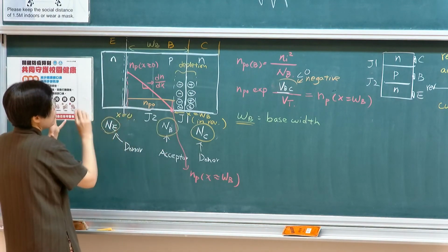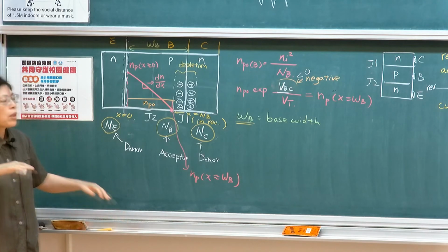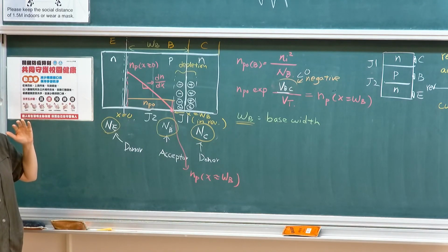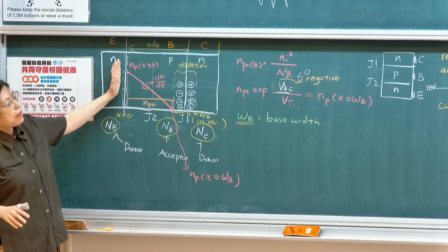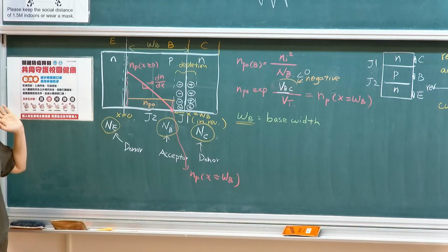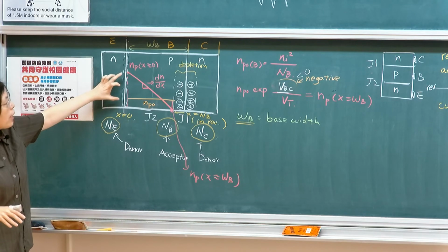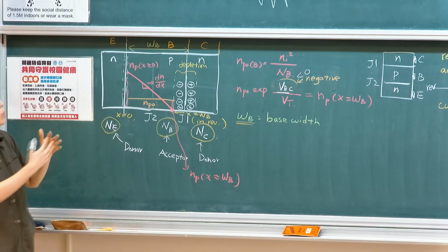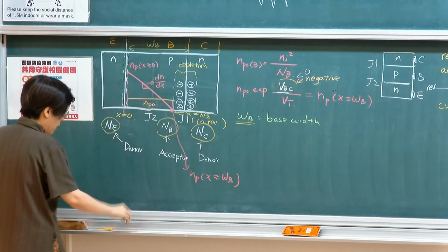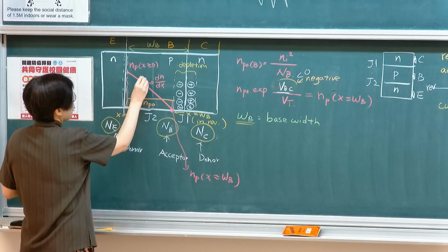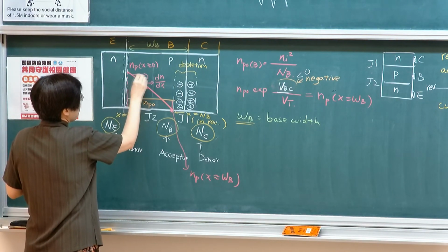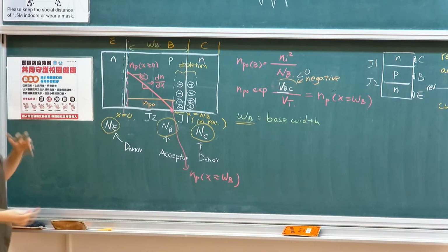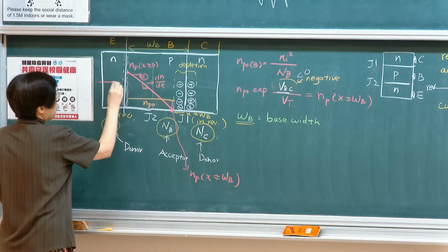We're going to get the numbers, but the basic idea is that you pull down the minority carrier concentration at the collector end, and you pull up the electron carrier concentration on the emitter end. So then we create a slope so that the electron will actually come in. So this is the electron diffusion current. You create a large profile, and then this current will come in.